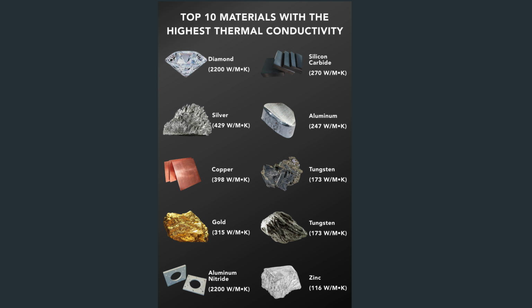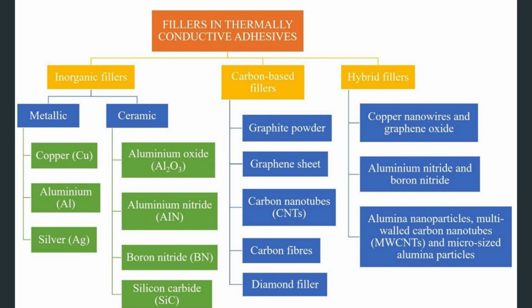The addition of fillers enables the formation of continuous heat transfer pathways within the adhesive. When the filler concentration exceeds a critical threshold known as the percolation threshold, filler particles establish a three-dimensional conductive network that significantly improves thermal conductivity.